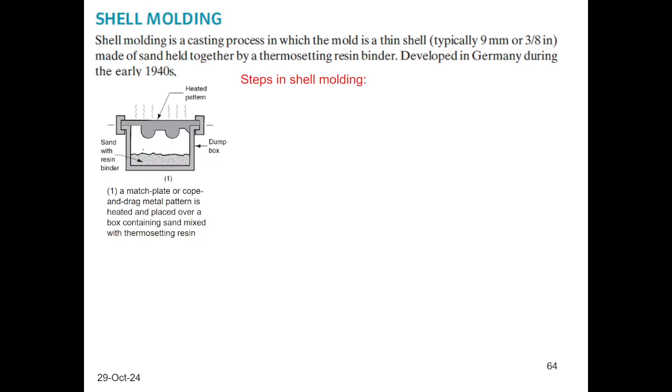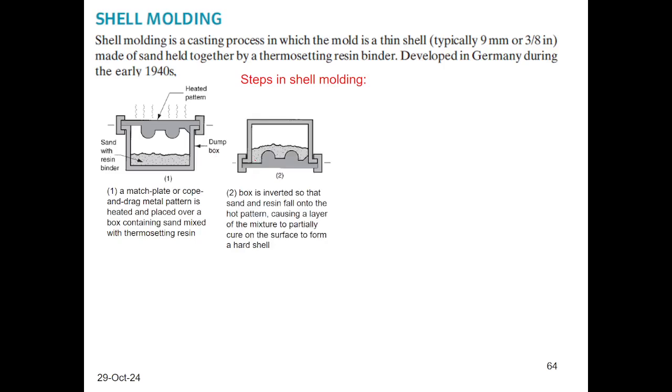Within the dump box we have a sand-resin binder mixture. And then we invert the box, and the sand and resin mixture rains toward the pattern.